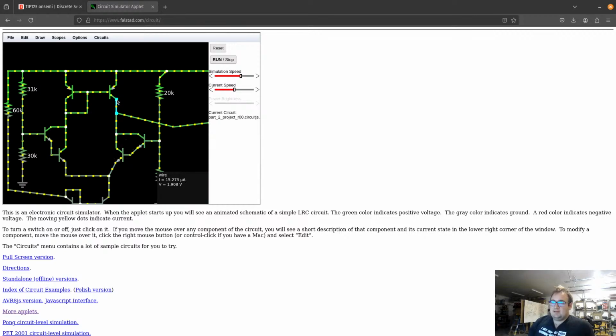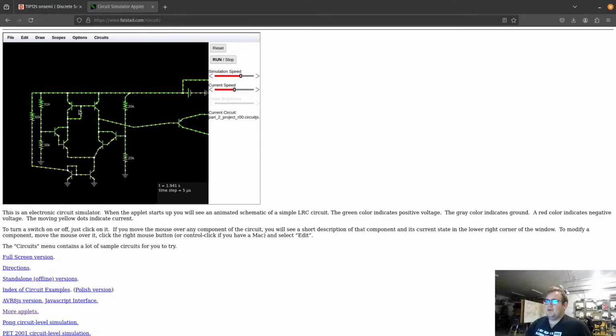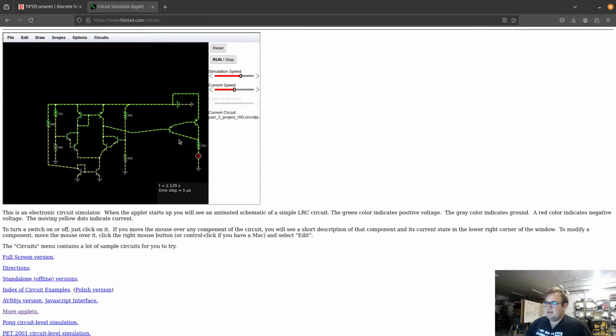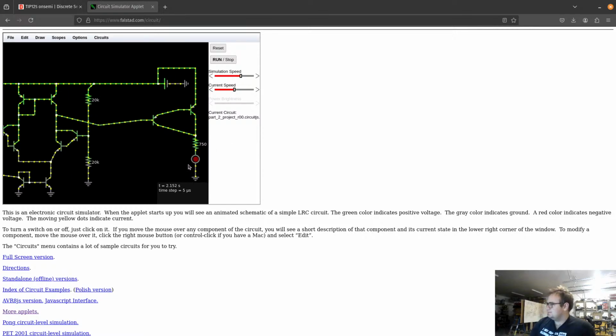What that effectively does, because this one here will be applying the same amount of current, but when we decrease the voltage applied here, decreasing the current being pulled out of these bases, which decreases the current coming this way, well then we start asking for current from here to match the current that's coming from here. And then that turns on this LED over here.